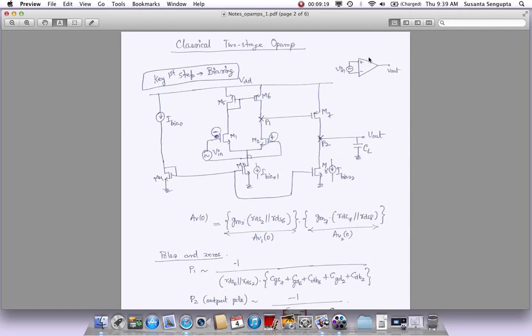As we said, this is an op amp like this, where the input is here and the output is a single ended output, and we want a huge voltage gain, as high as possible here. We want high output impedance, which, since we use MOS, these are high output impedances anyway, but these impedances will go down at extremely high frequencies, because what you see there is capacitances. There is no resistance, but there are capacitances that you see, parasitic cap. But at least for the majority of the operation, we will be able to see a high impedance there. Output impedance, I think we'll talk about it more later on, how we do the output impedance and all that. So this is a classical two-stage op-amp that is there, and we'll go into a lot of details.